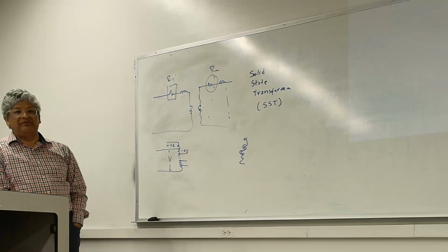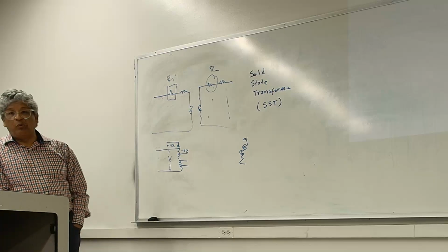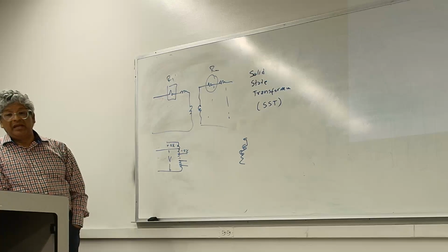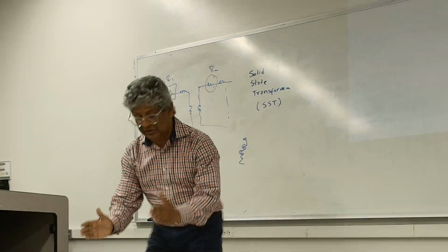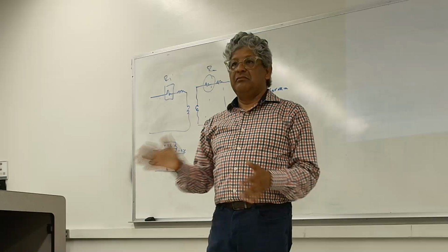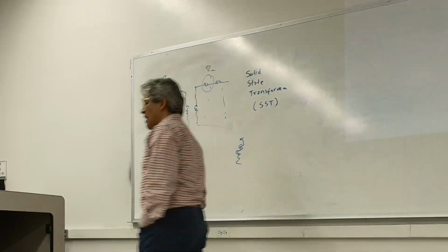Even the firefighters won't put water on it. It just goes until they completely melt, and then they have to do the cleanup. What Edison started doing after that was putting retainer walls between transformer banks, so that if there is a fire, you contain the fire in that one leg.